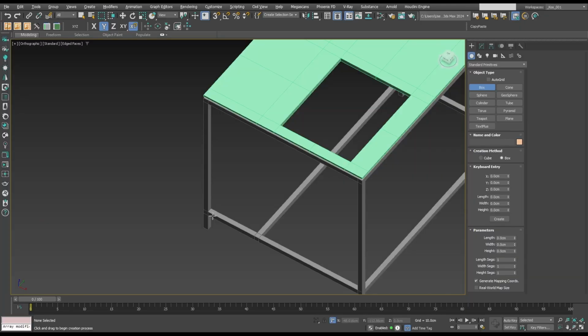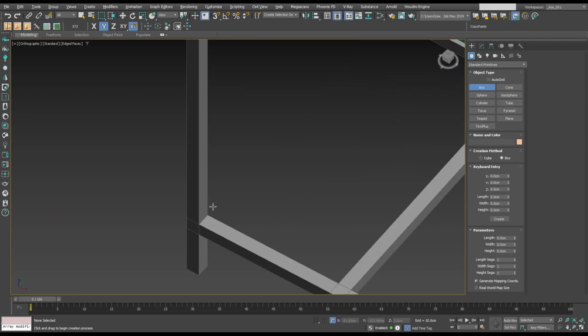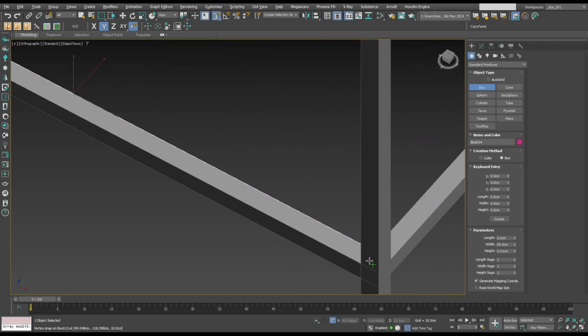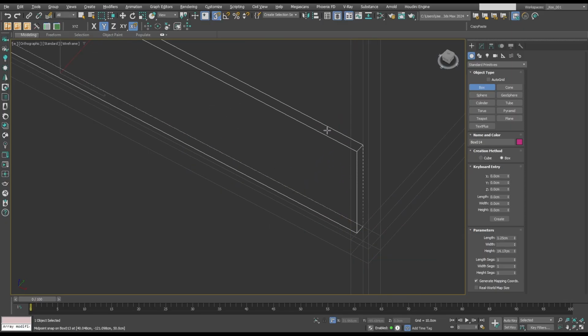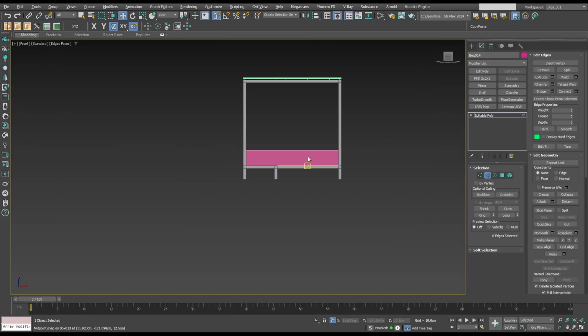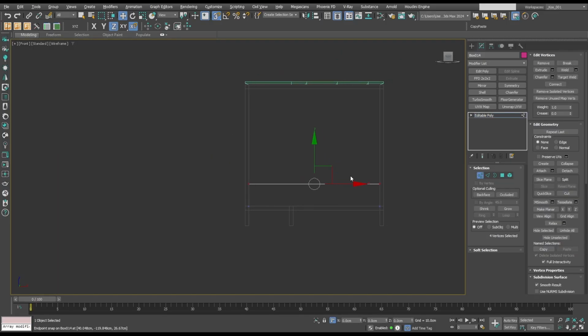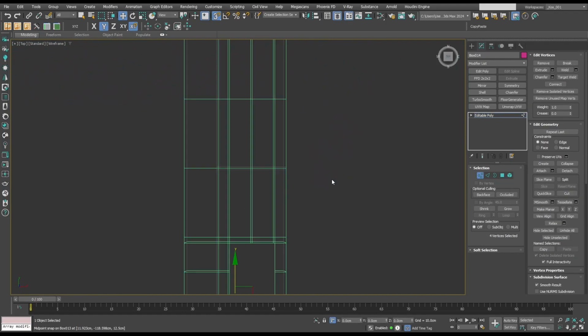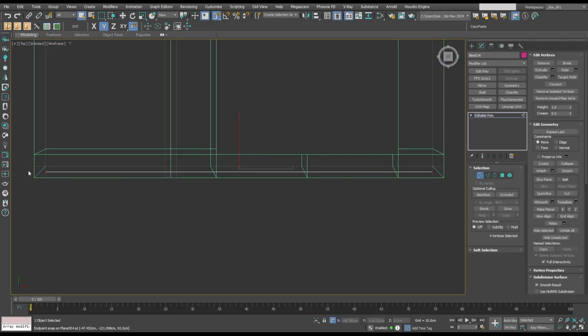The side panels are 1.6 centimeter thick wooden panels pressed with stainless steel and will cover basically the cabinet boxes. Okay, snap it. I collapse it into an editable poly, and go and give the right thickness. Select the vertices. Minus 1.6. Now what I can do,